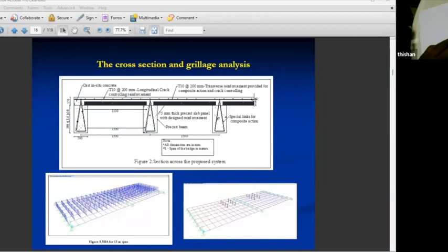The reason is every 1.5 meter or 1.8 meter, you get a beam. Because there's a beam, we can retain the stiffness of the structure, but we remove the unnecessary concrete, and in doing so, we reduce the weight of the structure. So actually, the weight of the structure can be about 50% of the live load.